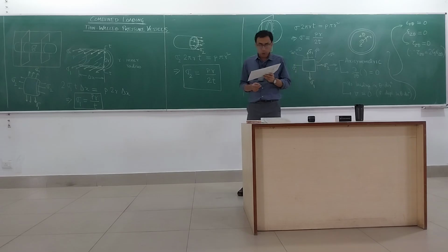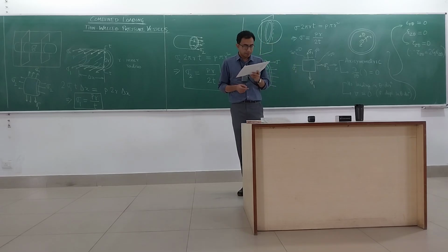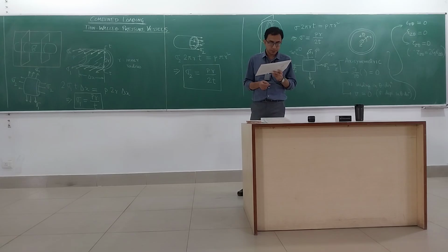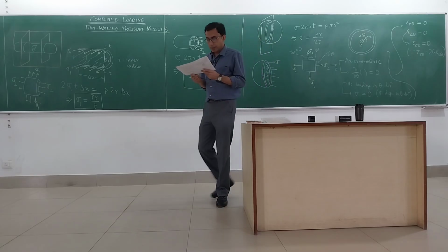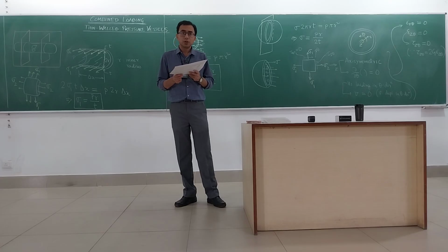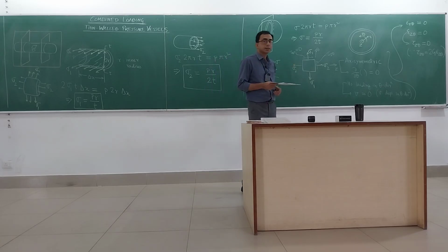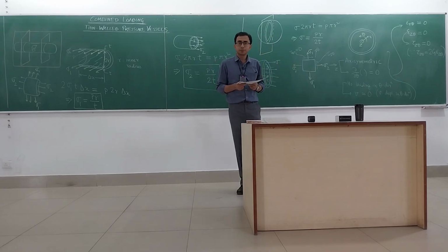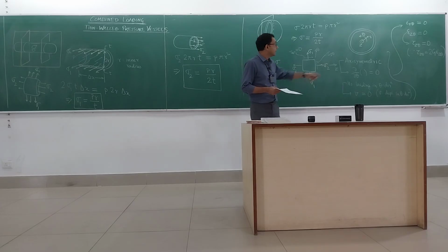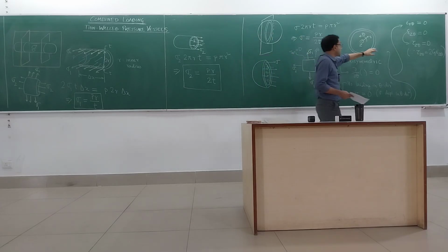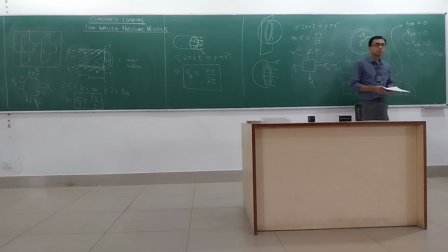That means that no matter what the value of u is, you will have the del u del theta term equal to 0. The first term in epsilon r theta, del u del theta, is equal to 0. The next two terms, del v del r minus v by r, are also 0, not following from axis symmetry, however, but following from the condition that you have no loading in the theta direction. The v itself is 0. So that is why epsilon r theta is equal to 0.